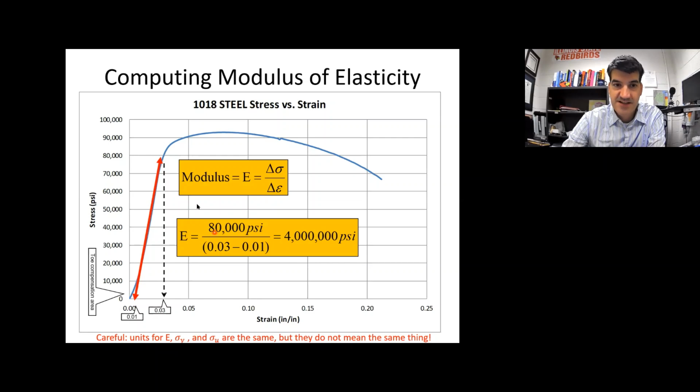So for this calculation, if you had this curve, you could pick a point right here. Say that's one of the points you'll use to calculate the elastic modulus. And if you draw a straight line down, it doesn't actually matter whether your point is on that curve. It just has to be on the extension of that curve, because you're just trying to calculate the slope of that line. So to calculate the slope here, we've picked this point right here, which is an extension of that linear region, and this point right here.